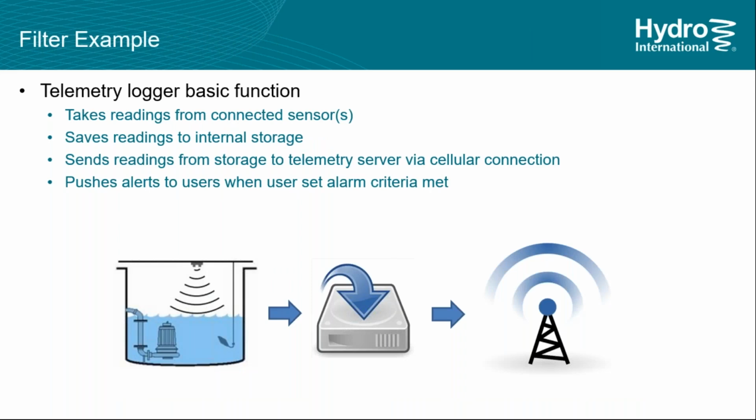Essentially, what we're able to do is tell you how much water is in the unit at any given time, what the water elevation is, how quickly water is moving through the system, whether the sump is at 25, 50, 100% capacity, and it's taking all this information, moving through satellites and putting it on your smartphone or your laptop, whatever it may be, but you no longer have to look inside these devices to know what's going on.